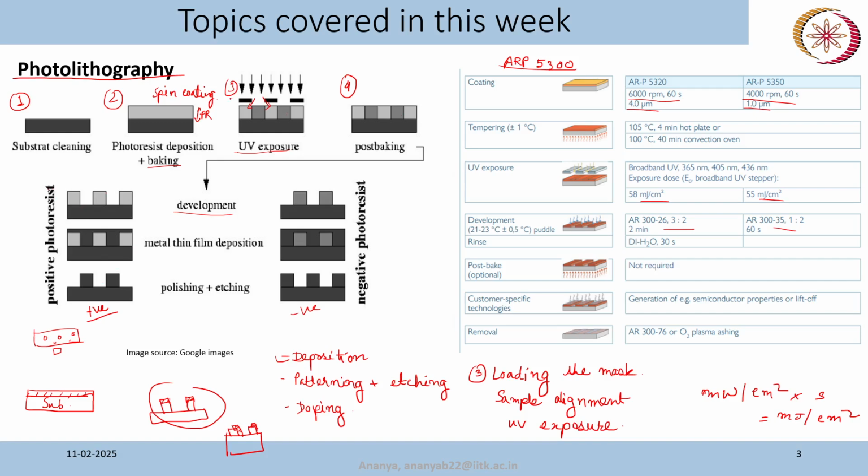You can see here, using the same mask with different photoresist, positive and negative, we can get a complementary kind of structure. So basically, this mask, normally the facility is not available, we normally make it somewhere. Depending on your resist, you can make different types of design. If you design a mask properly, then you can make it useful for maybe two applications with different types of photoresist. Okay, now after development, the process is given here.